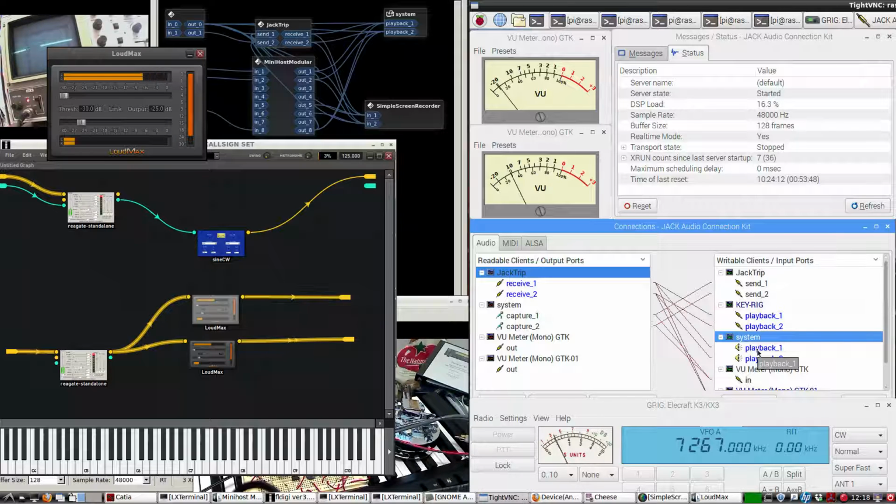But on CW, you can do AFCW mode, which I haven't enabled on the K3, but it has to be at a certain volume in order to activate the VOX threshold, as well as the CW keying switch. So if I shout or something, then it'll activate that CW keying switch. But my mic volume here is so low that there's not enough energy getting to that CW keying switch, which is key the rig.